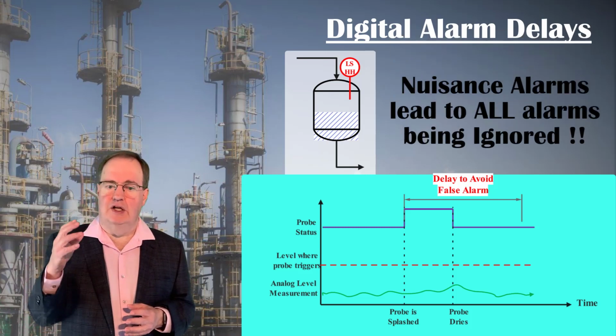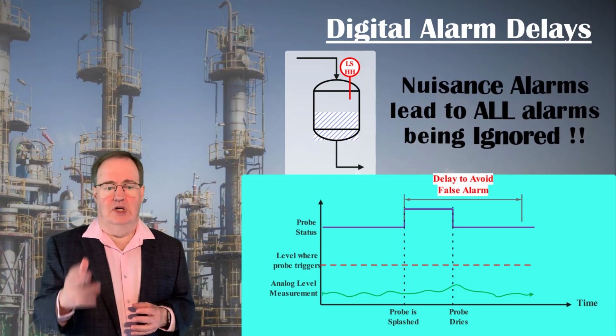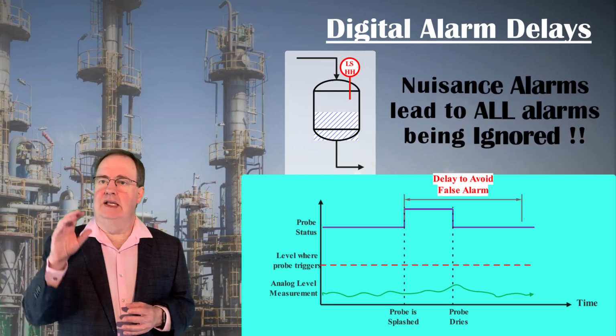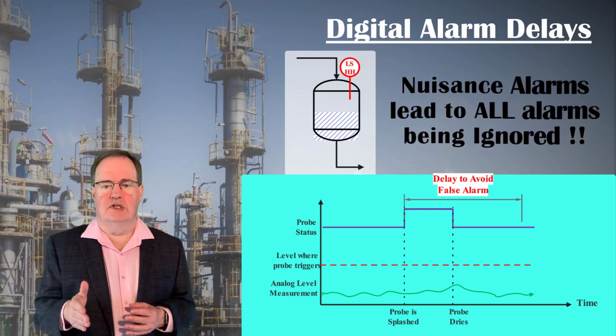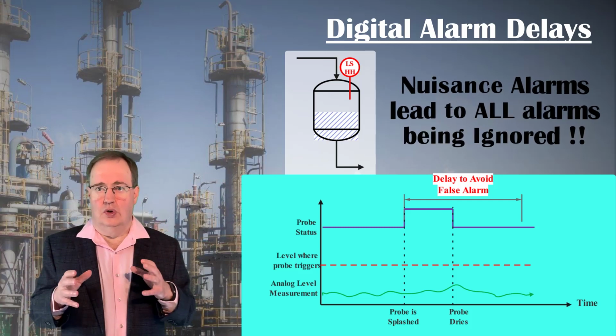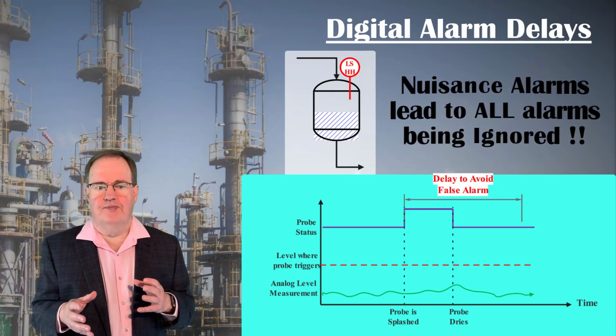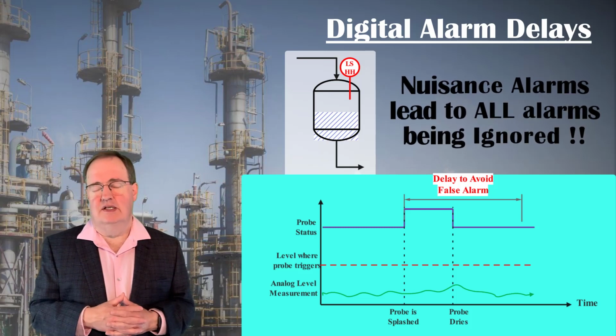Documenting and eliminating nuisance alarms is a task that can take weeks or months after a startup, but it is essential. A control room with lots of nuisance alarms is a control room where alarms get ignored or turned off, which is a failure of engineering at least as much as it is a failure of the operators and their management.